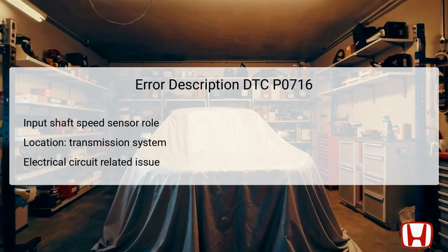The error code P0716 refers to the input shaft, main shaft speed sensor, which is essential for the functioning of the automatic transmission. This sensor is primarily responsible for transmitting the speed of the input shaft to the engine control unit, ECU, for processing. The location of this sensor is typically within the transmission housing, allowing it to effectively gauge the main shaft's rotational speed. This data influences the transmission control, ensuring timely and efficient gear shifts.